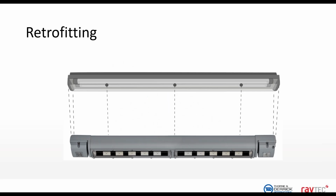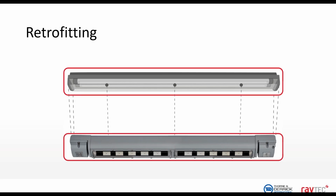And if you're retrofitting, if you're replacing an old fluorescent fitting, you also need to consider the luminaire's dimensions, cables or cable entries, and its fixing centers. So we'll quickly run through each of these. The dimensions: the replacement LED linear should be the same size as your existing fluorescent, traditionally 2 foot and 4 foot sizes. A replacement luminaire of the same size means the existing cables won't have to stretch any further, so they can still be used on the new installation.